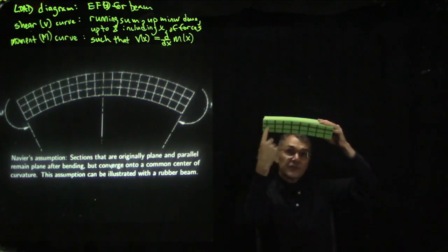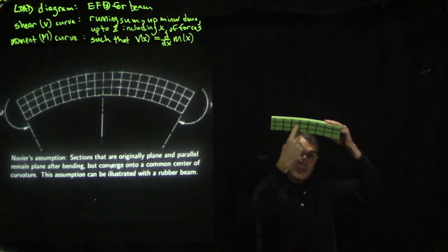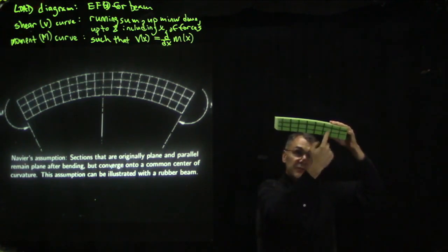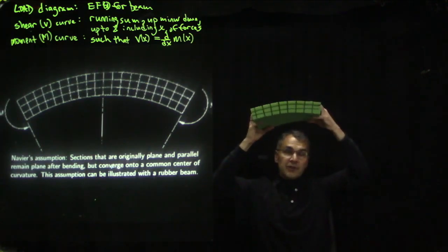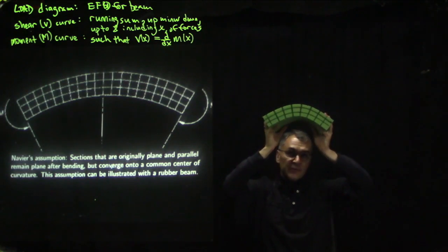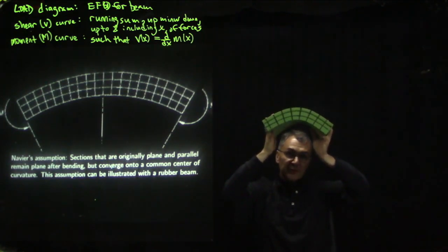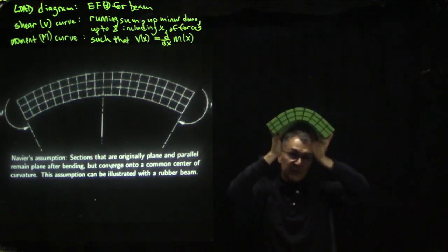So the neutral surface, if you have a uniform material and a rectangular cross-section, is right through the middle. If you have a uniform material, the neutral surface will be through the centroid. And many textbooks, Onouye's included, include some drawings that show the history of thinking of what happens to a piece of material when you load it like this. For a long time the thinking on this topic was incorrect. It took a while for people to understand that in fact there is a neutral surface in the middle, and then in a situation like this the bottom is in compression and the top is in tension.